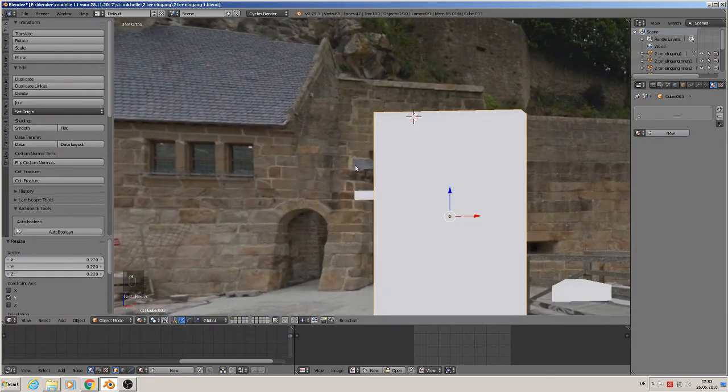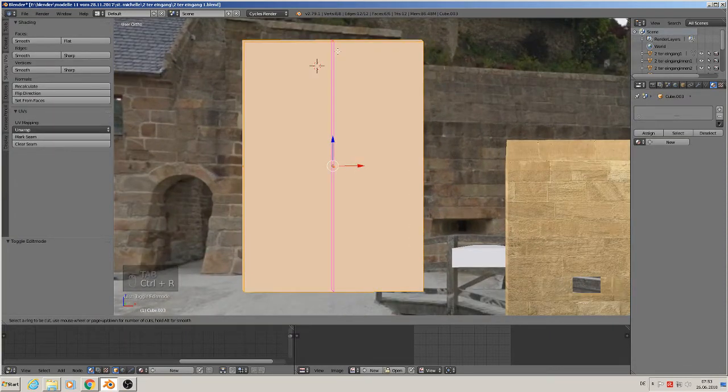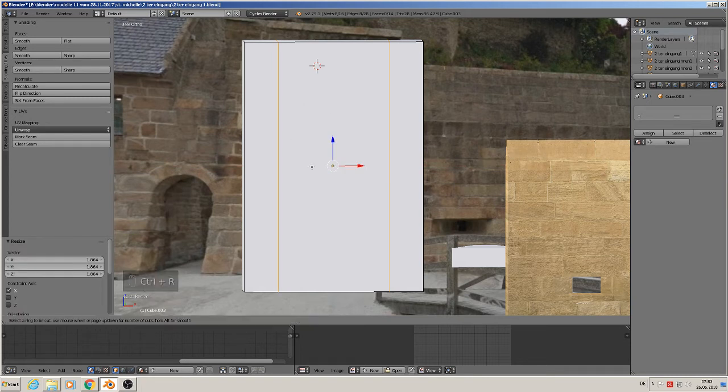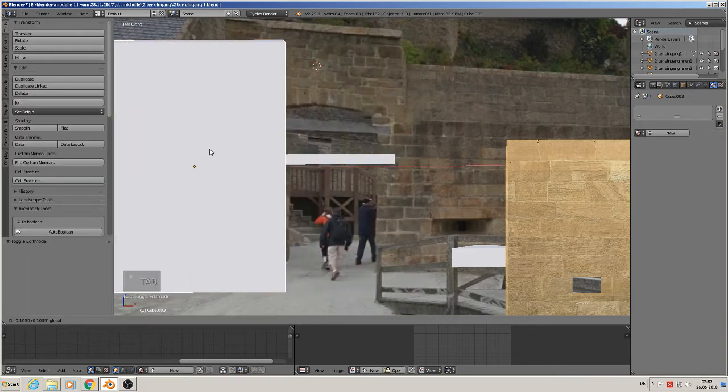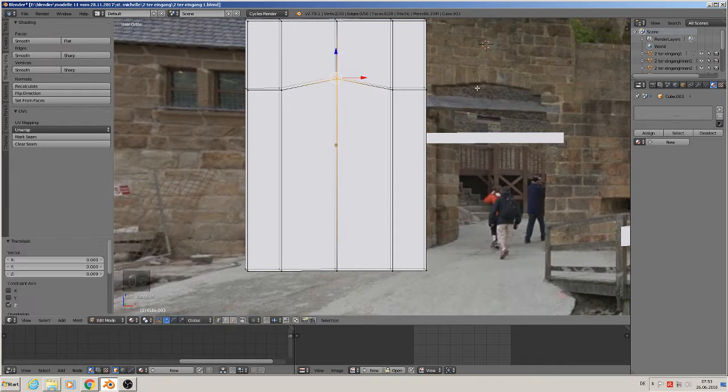And then we only have to cut in this door there, so we go edit mode, Control R, make 2 loops in, roll the middle mouse button to get 2 loops, scale X to bring them more to the outside, Control R again, make a middle loop to the top part there, and now we have to split that up here, so we Control R, make a middle loop, and then we take here this middle verts and bring them a little up, so we have already what we want.